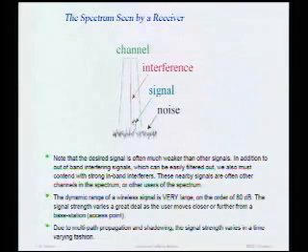So as I've shown in this picture here, you can see that in general you have a channel. The channel is a frequency span over which you're communicating, and this little spike here is your signal. I'm not sure if it shows up very clearly there. And you might have a huge interferer sitting right next to you. Now you might say, well, where did this interference come from? Just suppress that interference. Actually, that interference is someone else communicating over a channel right next to your channel. Or it could be some other source of interference that you have no control over. So you can't simply gain up your own signal, because then you'd also gain up the interferer, and eventually the interferer would make your system clip.